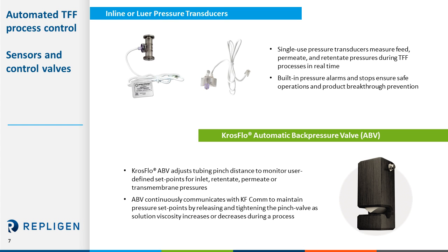For those who perform TFF, you know that it's important to understand the pressure profiles of your process. Knowing the pressures within your system is a good way of tracking the performance of the membrane being used, and also a key parameter for scaling up process in the future. Inline or Luer-connected single-use pressure transducers are key components of the KR2i and allow for real-time process monitoring of feed, permeate, and retentate pressures.